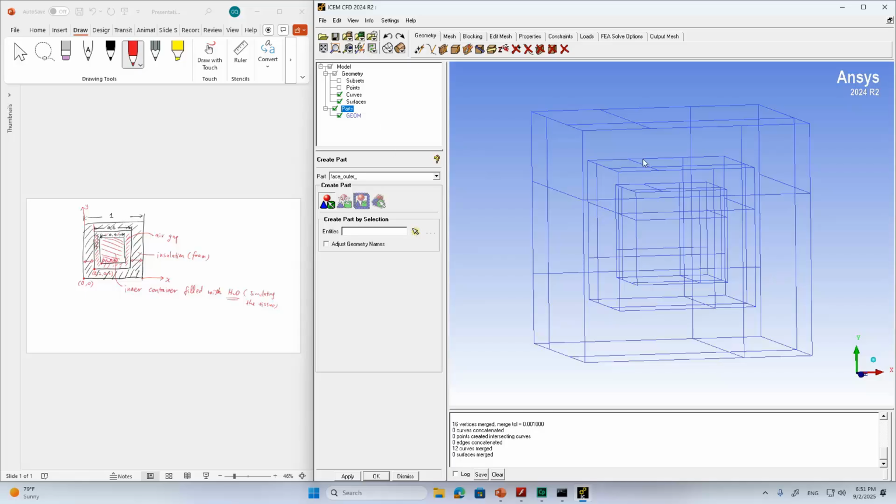Because according to heat transfer, the natural convection at the top surface is different from the lateral convection along the vertical side surfaces, which is also different from the convection at the bottom surface. So you want to differentiate these 3 types of surfaces, but here for simplicity I will lump all those outer surfaces in one part.